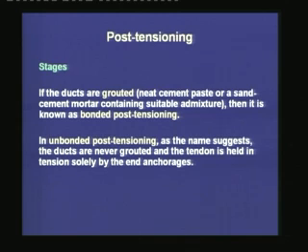Now, after the tensioning operation, if the ducts are grouted, then it is known as bonded post-tensioning. Grout is a neat cement paste or a sand cement mortar containing suitable admixtures. Now, the grouting is done to prevent the steel tendons from corrosion, and after the grouting there is a contact between the concrete and the steel through the hardened grout.